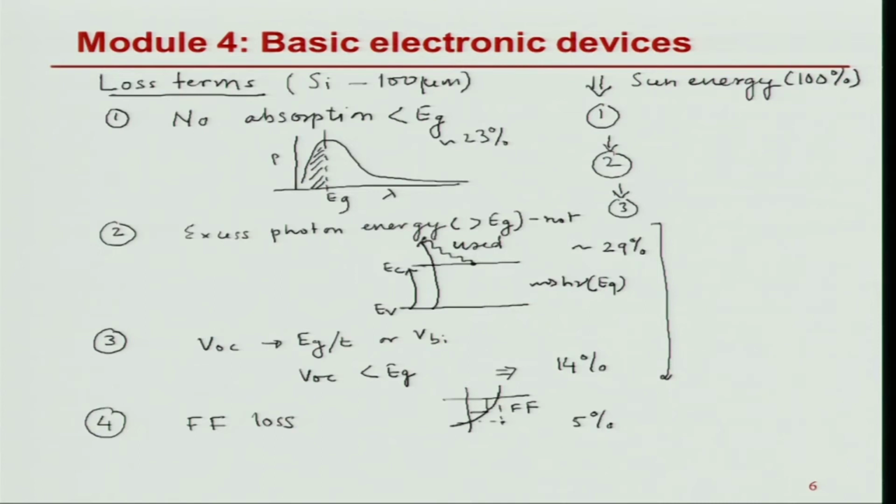And this is just from a typical PN junction that I have just calculated assuming ideal values. This is a loss that I am going to see. So, this is my theoretical PN junction efficiency for a silicon device, and it comes to, for a single junction, about 29%.